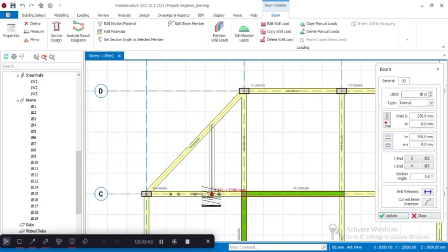So if I want to, I can select now. I've created my beam resting on other beams. This is the secondary beam. These are the primary beams, if I'm understood. Pressing Enter while the cursor is at any of the snap points will allow input of the exact distance from the start of the beam.